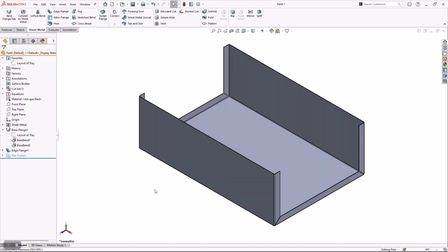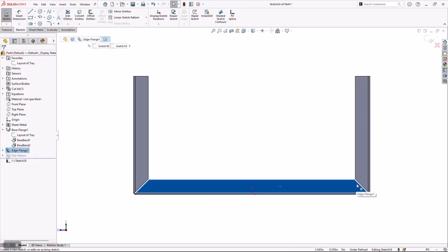Now I've got a good piece of this started, but I need to finish this part by creating a second part. Essentially think of it as an assembly. As opposed to creating another part that is a standalone part, I'm actually going to leverage what we call multi-body modeling, where I'm going to model the second end cap in context of the first part.